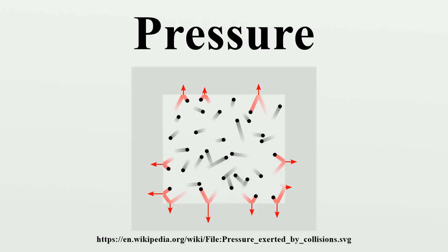making any lasting impression. However, the same finger pushing a thumbtack can easily damage the wall. Although the force applied to the surface is the same, the thumbtack applies more pressure because the point concentrates that force into a smaller area. Pressure is transmitted to solid boundaries or across arbitrary sections of fluid normal to these boundaries or sections at every point. Unlike stress, pressure is defined as a scalar quantity. The negative gradient of pressure is called the force density.